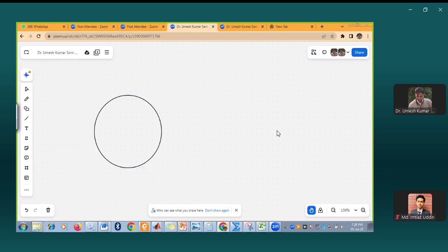We are defining this circle as a stator, and here we have HA, that is Hall sensor A. Here HB and here HC. It is placed under the core and it is pasted. This IC is pasted and we provide the external supply to this IC.